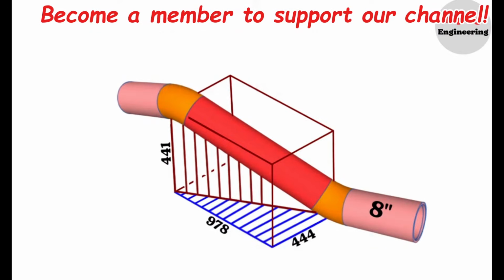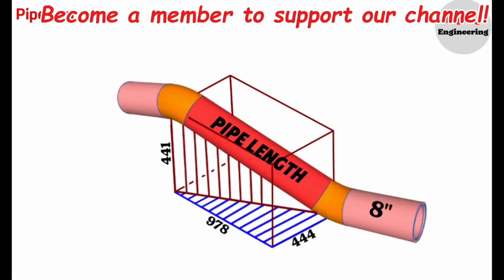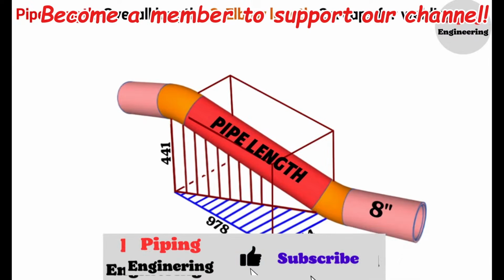To determine the length of a pipe section between two elbows in a pipeline, we will follow these steps. Calculate the overall length and the center-to-center distance between the two elbows. Determine the angle, length of the elbows, and their takeoff dimensions. Finally, subtract the elbow lengths and welding gaps from the overall length. The formula can be expressed as pipe length equals overall length minus 2 times elbow length minus 2 times gaps for welding. We will perform all these calculations step by step on this 8-inch pipeline section.